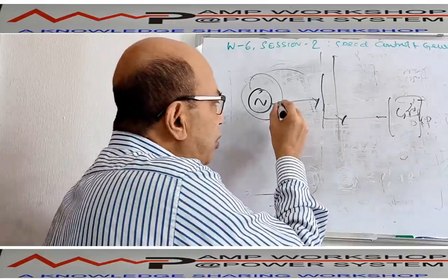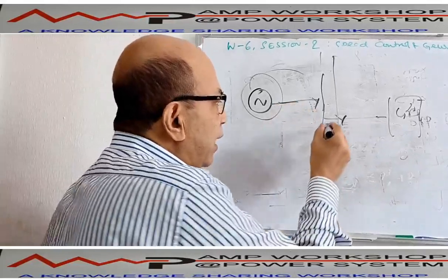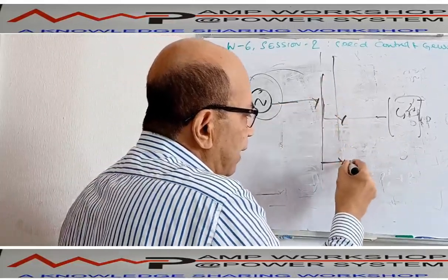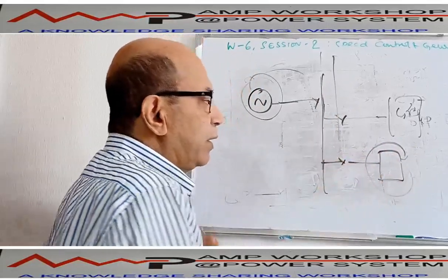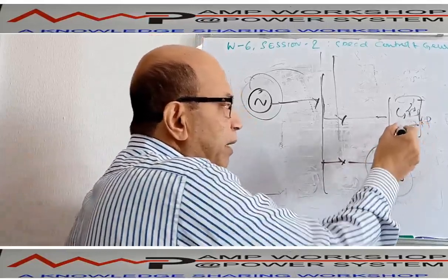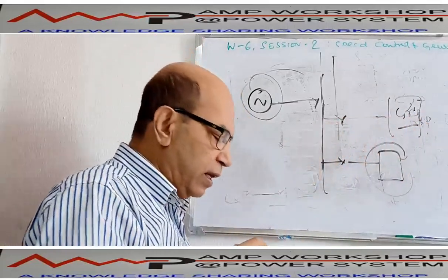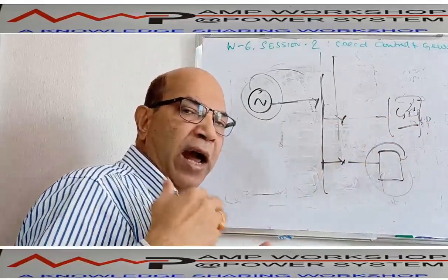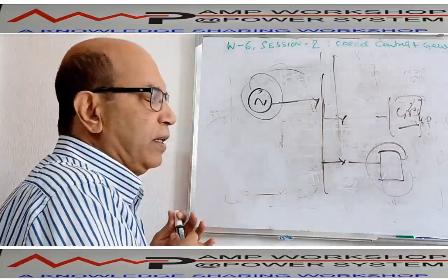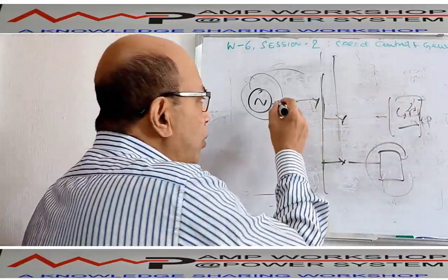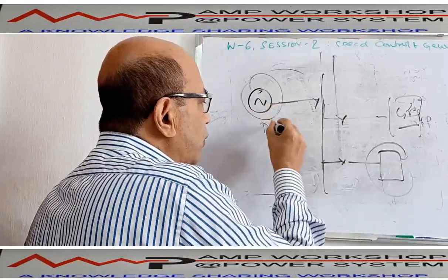These are the buses where the loads are connected. Whatever loads are connected over here will be taken by the grid, because the grid is maintaining the frequency. The grid is an infinite source. You cannot change the frequency of this bus. In that case, what do we do? We put the machine on the Droop mode.